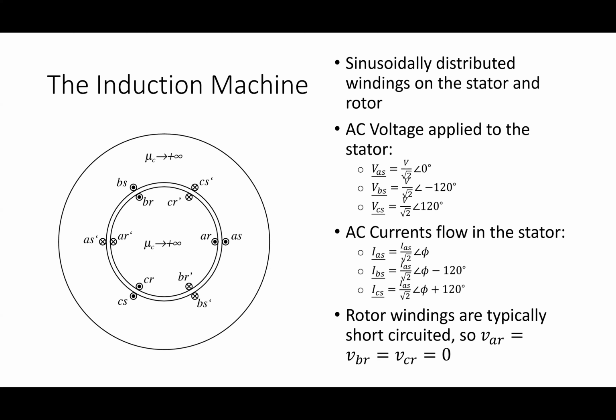How did this thing work? Well, at zero speed, before the motor starts, you have the rotor sitting there stationary. You put currents into the stator windings, and you have a magnetic field that starts rotating around the air gap. That magnetic field rotating around the air gap did what inside the rotor windings?